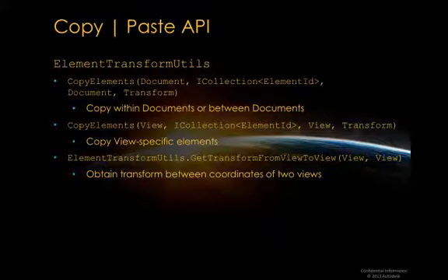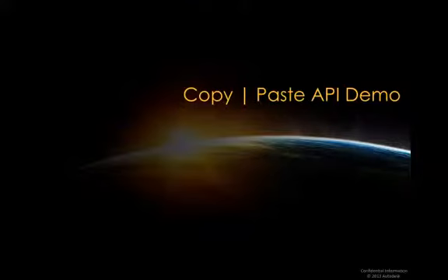New methods have been added to the ElementTransformUtils class to copy groups of elements within documents or between different documents. You can copy view-specific elements. You can obtain the transformation between coordinates of two views. To demonstrate this, we have the following demo.